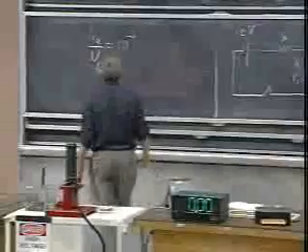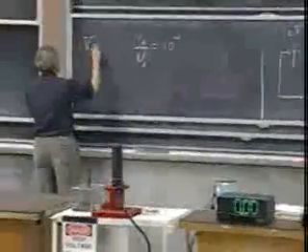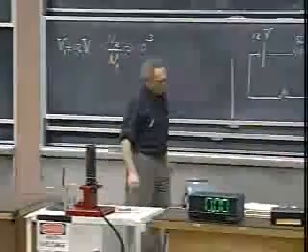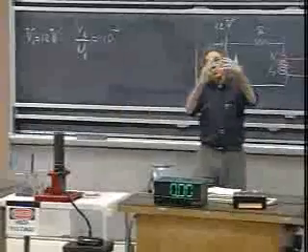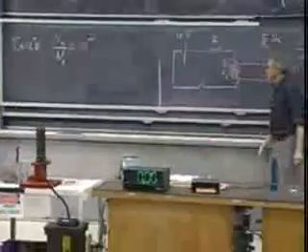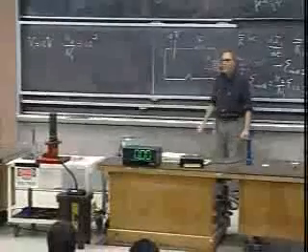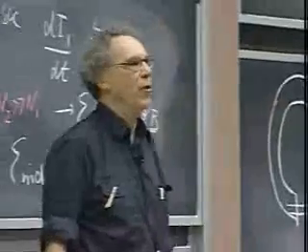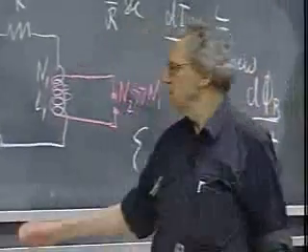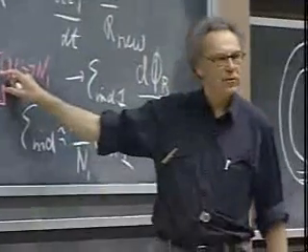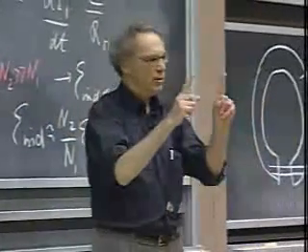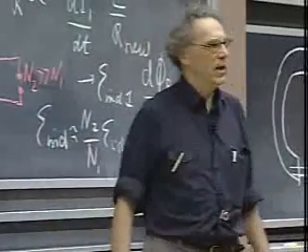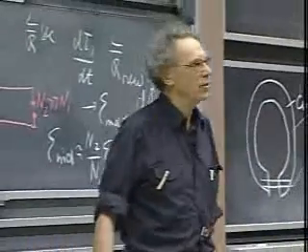And we run it with a car battery, just like your car, 12 volts. We let the current build up in the primary, just like we have here, and then in a very cruel way we open the primary, and we create in the secondary up to 300,000, 400,000, 500,000 volts. And then you will see a spark fly over here. At 300,000, 400,000, 500,000 volts, you can draw a spark over a distance of 10 centimeters easily, because all you have to do is get above 3 million volts per meter, which is the breakdown electric field.